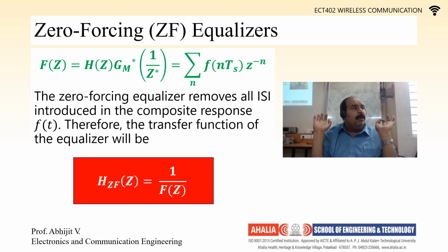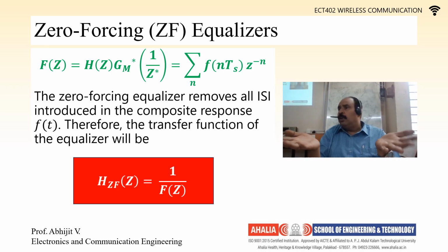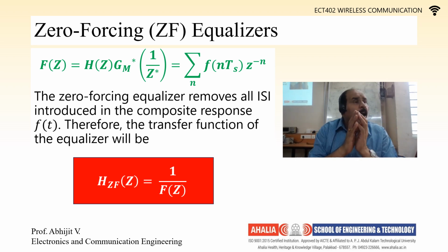Can you understand how it is eliminated? All of you understood how inter-symbol interference can be eliminated? You are taking the inverse of all the combined transfer function responses. So what you are supposed to get is nothing but the input signal without any ISI plus the noise. Noise is certainly there and noise is enhanced. If the noise increases, what happens? The performance of the zero forcing algorithm degrades. Am I right? Yes or no? Understood all of you clearly?